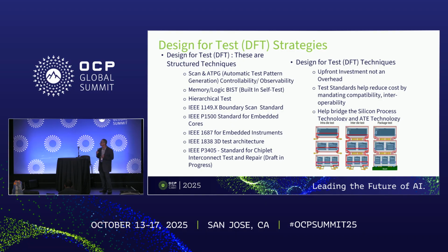Some of the standards are already used. For HBM, if you want to build an HBM stack, this IEEE 1500 is a core-level standard. Also, it was defined way earlier and has been adopted in HBM. This shows how you can go up the stack, send the test stimulus up in parallel, and get that response down at the bottom die, which is talking to the outside world or the PCB.